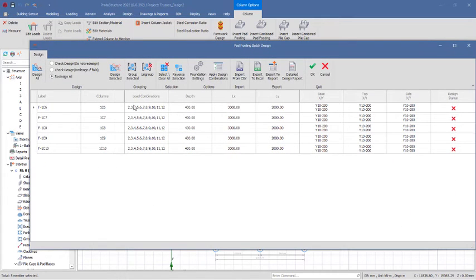So this is one of the disadvantages of designing by grouping, because it's going to give you larger sections of the footings. Alright, because it's going to pick the highest footing size and use it for all of the rest of the footings. So let's say we agree by this, click on the OK options, you have the footings inserted just like this.